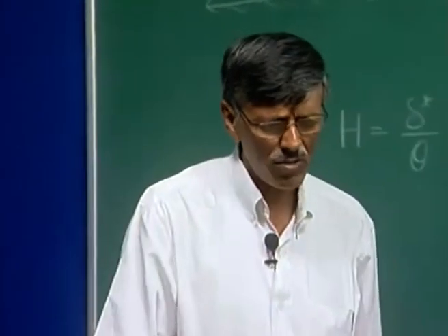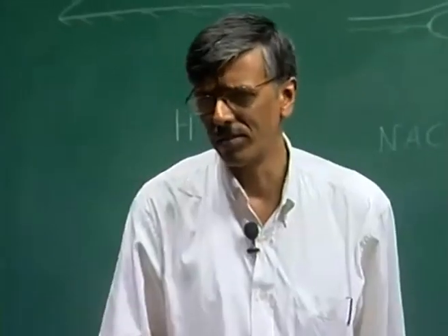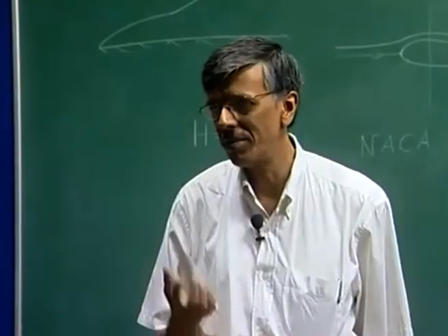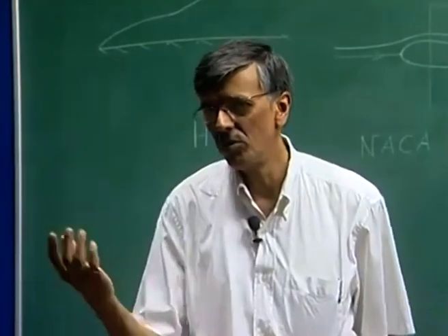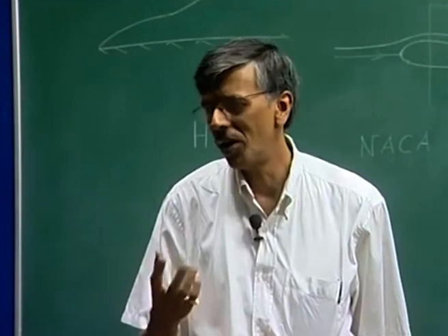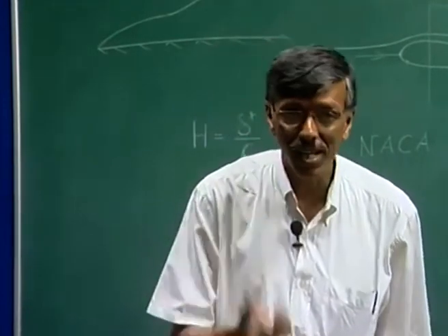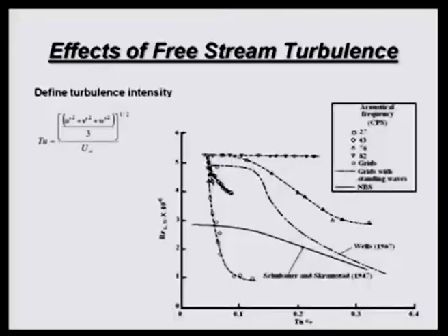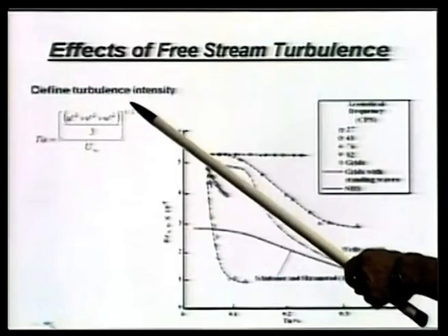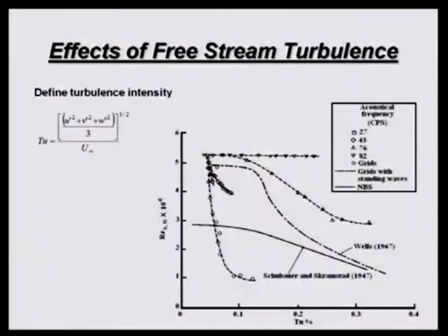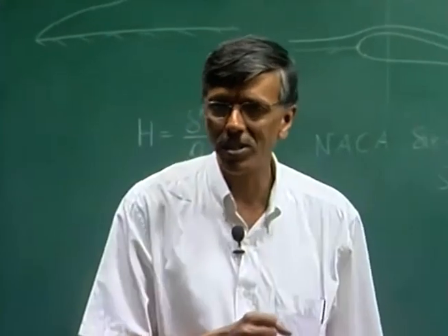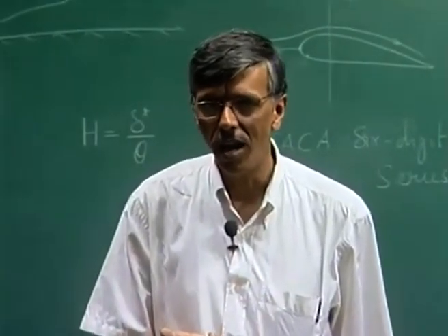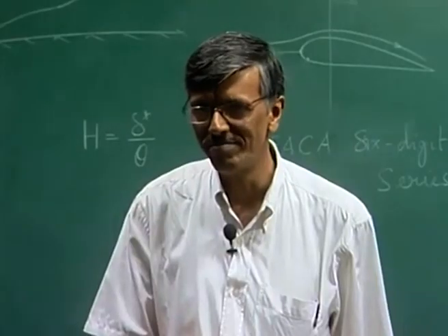if I am seeing a fluctuation, what is this? Any disturbance in a fluid flow can be classified into a few generic components. One of the components would be the vortical disturbances. I can create small eddies. Those could give rise to this u prime, v prime, w prime, right. That is your vortical disturbance. However, I could also create an acoustic disturbance, acoustic noise. Are these two things the same?